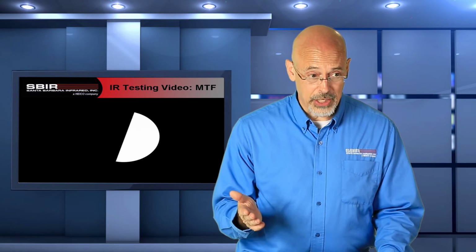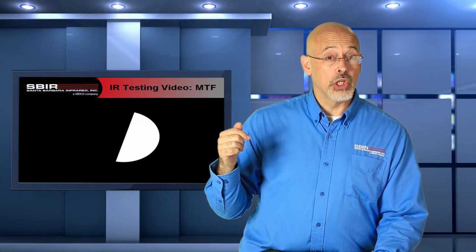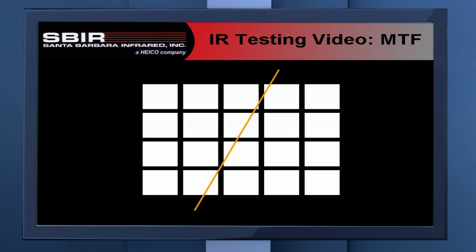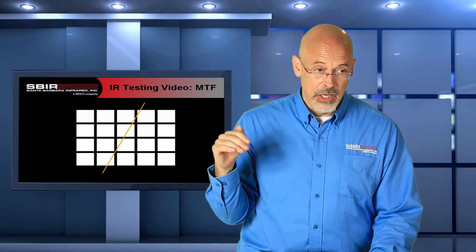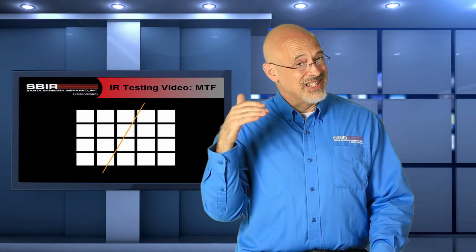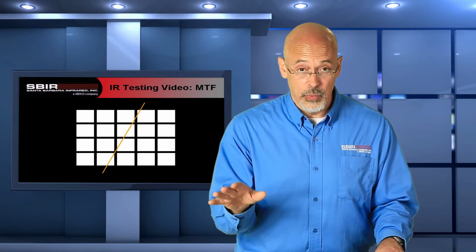It's basically the edge of a target, only we've got it at a slight slant. Now what we're going to do, and what we'll see in the next slide, is that we have the edge going along the elements where they cross at different places along that sensor element along each row. And what you have are different phases on every line. So if we take each individual line and do an MTF analysis on the line, we get different phase responses. After doing all the analysis, we can average everything in MTF space, and by doing that average, we can eliminate the phase problem by averaging out the phases. So that's one common way of dealing with the phase problem.